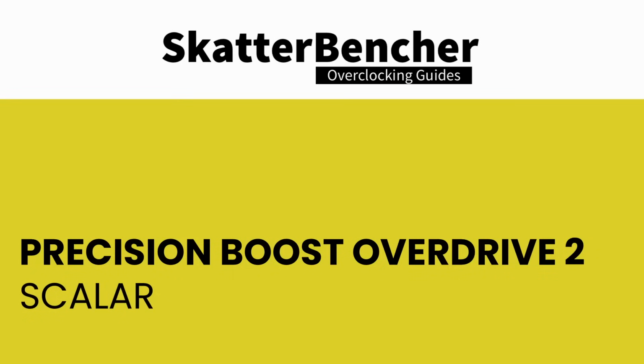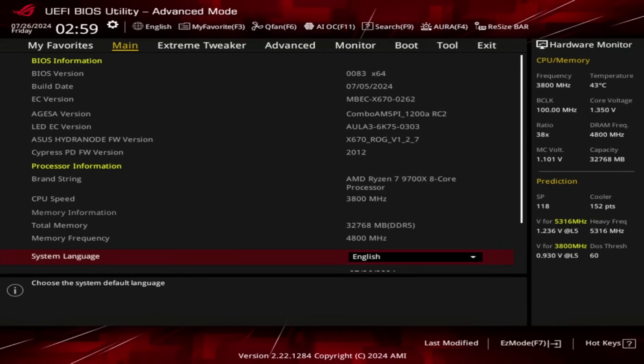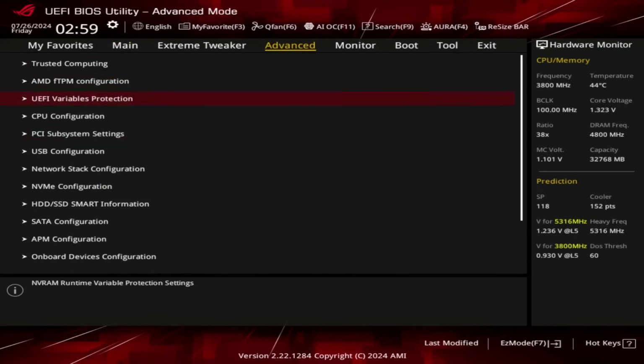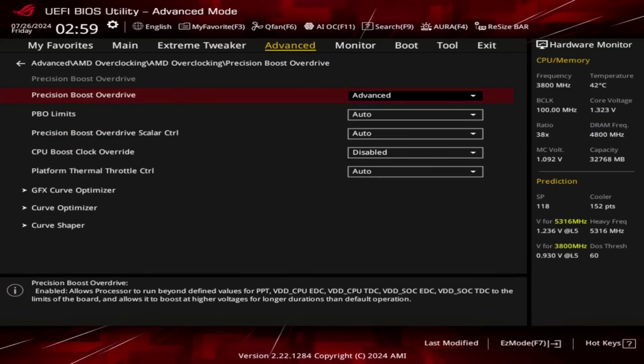Scalar is a tool that allows you to override the warranted stress level, or FIT, of your CPU. Essentially, you can increase it to 10 times the factory fused value. The tool's relevance shifts from architecture to architecture. For Zen 5 Granite Ridge processors, it appears Scalar is making a comeback in the overclocking strategies because the chips are very voltage limited. While the tool offers precise granularity, typically you'll find the available options to range between 1x and 10x in steps of 1 multiple.